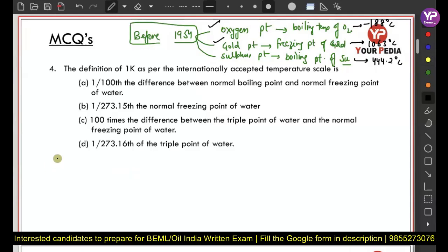So if you just see, in the temperature range of minus 188 degrees Celsius up to 0 degrees Celsius, which thermometer do we normally use here? We use a platinum resistance based thermometer here.